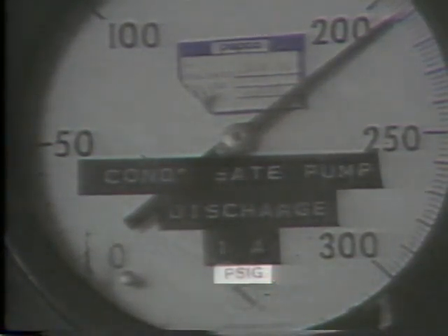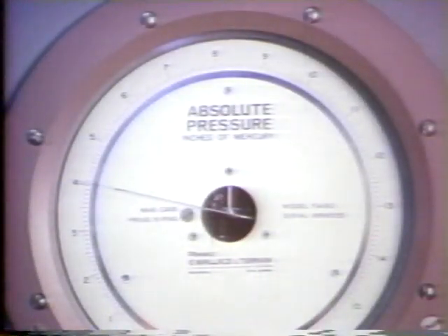On the other hand, some of the gauges in your plant do include atmospheric pressure in their measurements, in the same way that we did in the pool. This gauge, showing main condenser pressure, includes atmospheric pressure in its measurements. You know this because the gauge is marked absolute. Other absolute gauges may be marked PSIA.